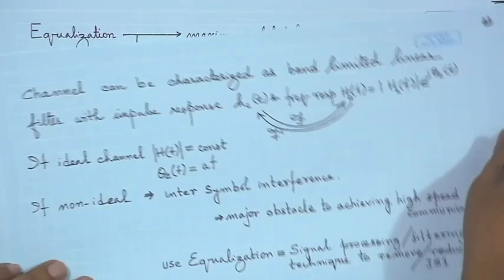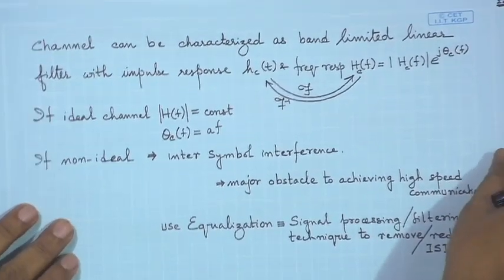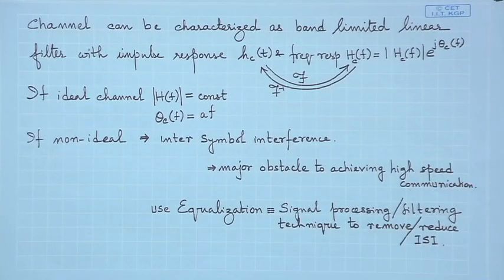So, with this we cover our discussion on techniques by which we can send signals through band limited channels. Just a quick summary: we could restrict our signals to a bandwidth of 2 W, but in that case we would stretch our symbol duration to be longer than the typical Nyquist, and the excess bandwidth could be used for a smooth roll off.